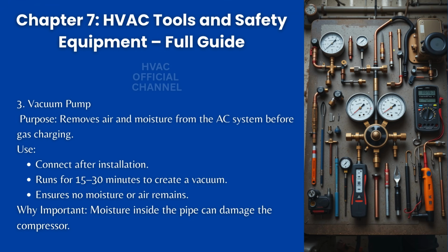3. Vacuum pump. Purpose: removes air and moisture from the AC system before gas charging. Use: connect after installation. Runs for 15 to 30 minutes to create a vacuum. Ensures no moisture or air remains.